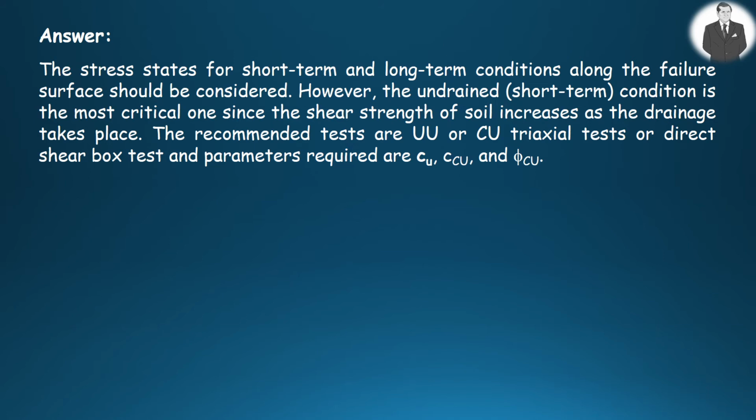So the recommended tests are undrained unconsolidated or consolidated undrained triaxial tests or direct shear box tests. And the parameters needed are cohesion intercept and the internal friction angle.